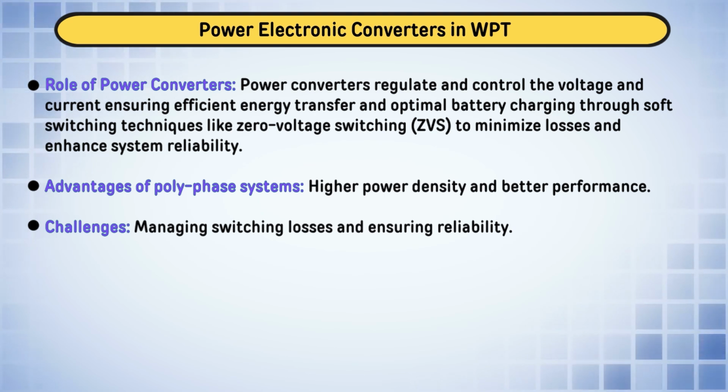So, this converter can perfectly work for V2G and G2V modes of operation, where the phase difference decides the power flow between input and output or output to input. The magnitude of current will be decided based on the phase difference between input and output, and the energy will be transferred.